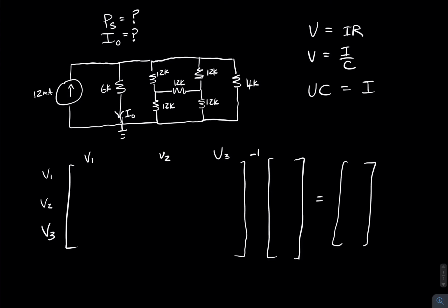Good morning, guys. So this is an old test question that I'm going to go over. And you can obviously see that this is a Y-delta question just by this kind of business right here. But I'm going to solve it using nodal analysis first.